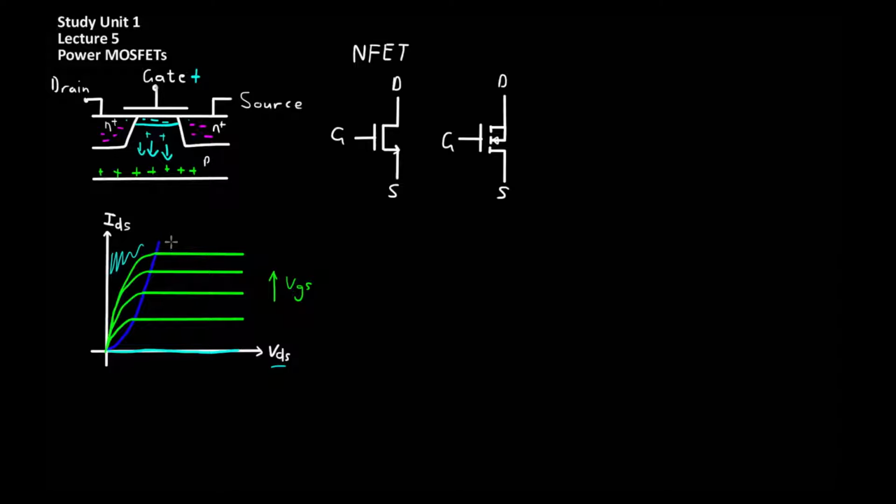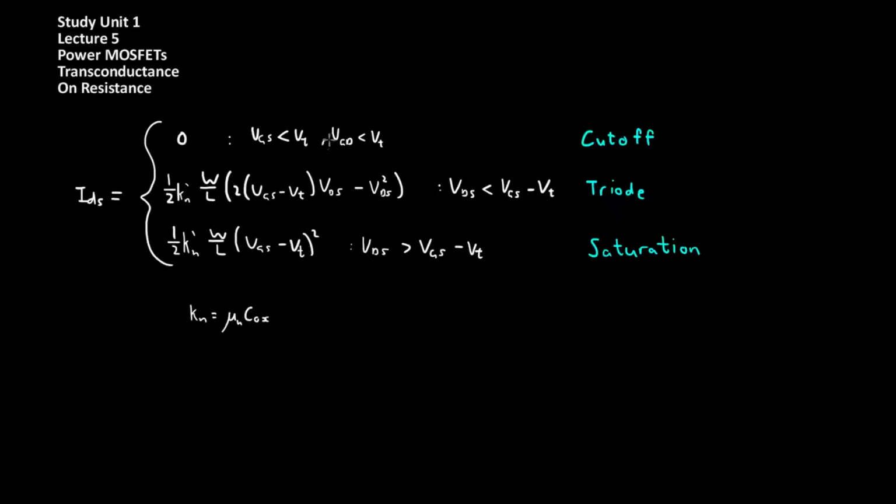The third and last region of operation is the saturation region. In this region, ideally, IDS is constant for all given VGS, regardless of the value of VDS. Essentially what happens is, as the transistor starts turning on, the current will eventually plateau and remain constant regardless of the drain source voltage. For each region of operation of the MOSFET, there is a set of describing equations.